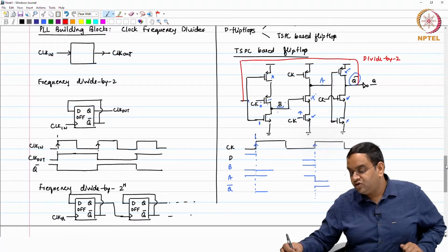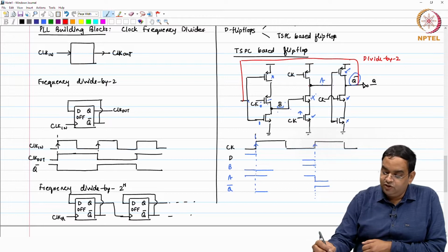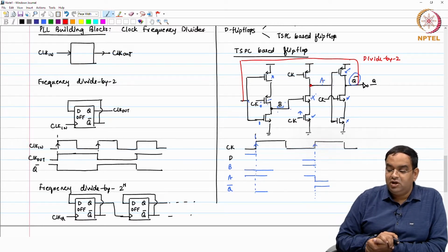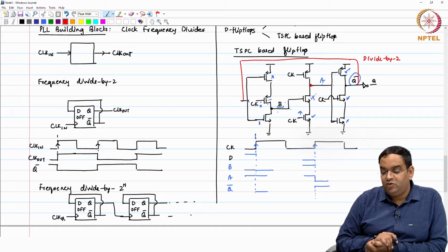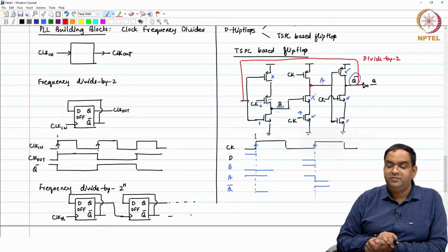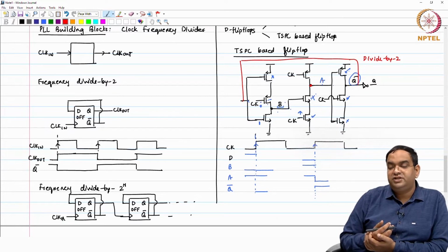The problem with this logic is, as the frequency of operation is reduced, these node voltages which are actually held at 1 or 0, right, they are not connected to VDD or ground all the time with a direct path. So, these nodes will start discharging, or you have subthreshold current, for a long off duration or long on duration in the different transistors.